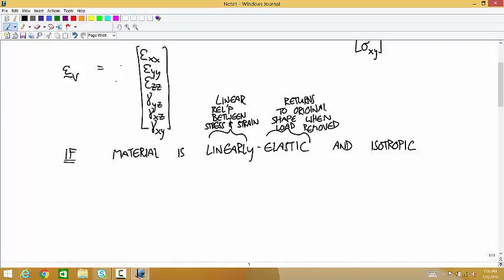What's a material called when you load it, remove the load, and it stays deformed? Anybody have a guess or happen to know this? That's true. But plastic. So when you talk about a metal going into its plastic region, or you talk about material plasticity, you're talking about something where you've deformed it past the point where it's elastic. Materials like steel basically are elastic.